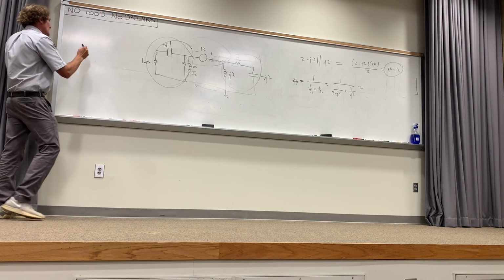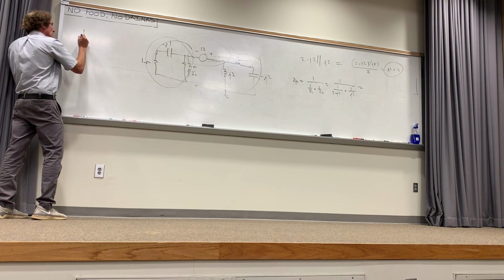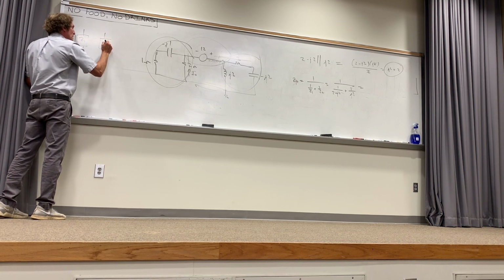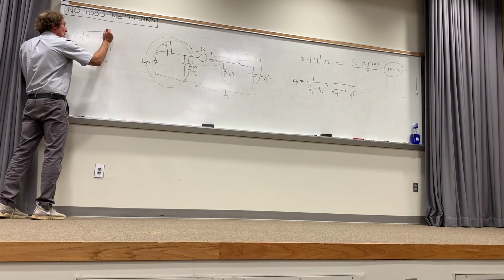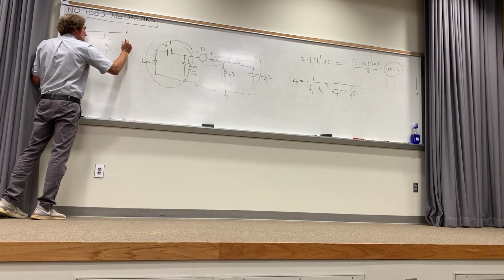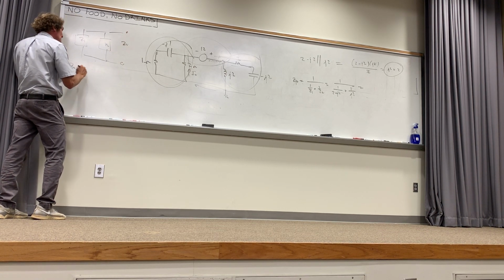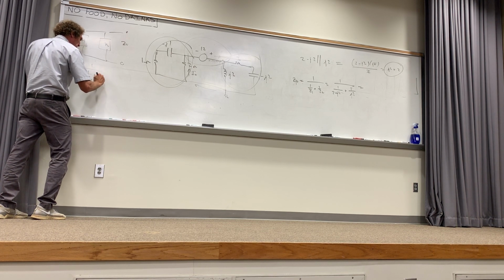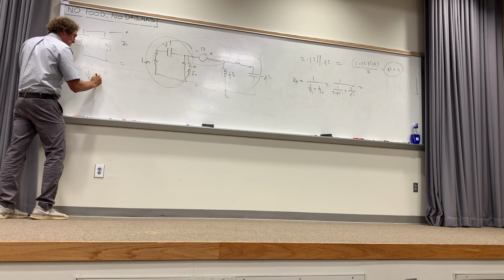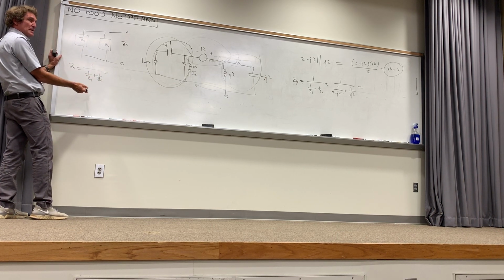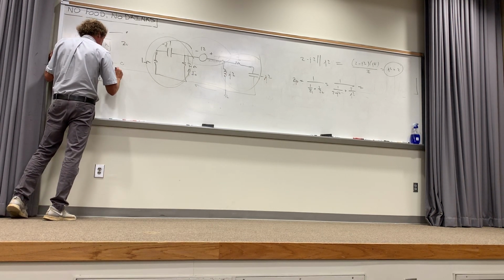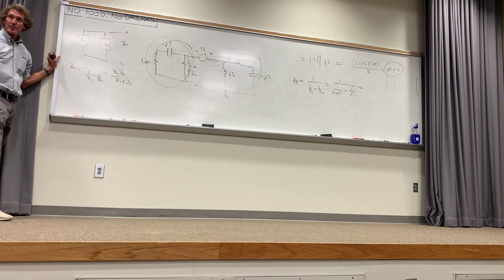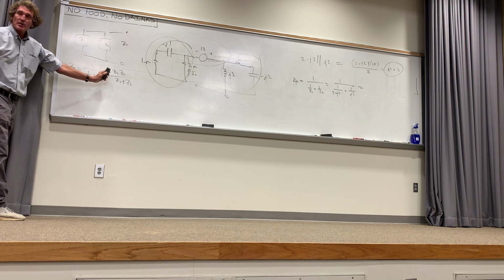In other words, just to be clear, if you have some Z1 here, an impedance, complex, it could be real, and some Z2, and I wanted to know what the effective impedance here is, Z net would just be equal to either 1 over Z1 plus 1 over Z2, or just take this equation and multiply top and bottom by Z1, Z2. Then you get Z1 Z2 over Z1 plus Z2. You all see that, class? This is the one I'm using here.